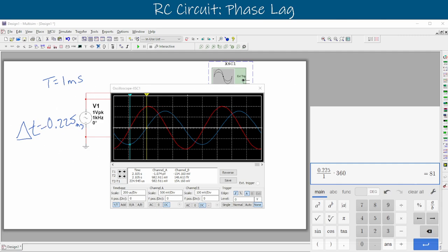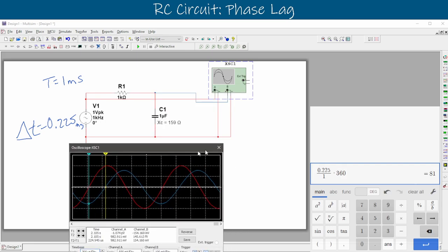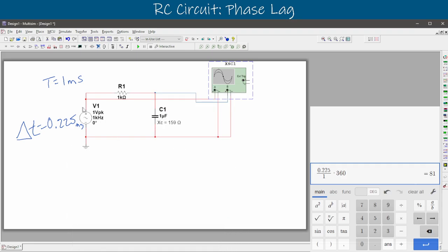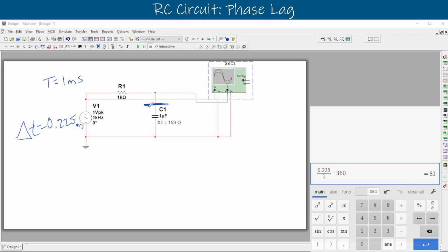So is this actually a high-pass filter, or a low-pass filter? Our signal is going to come up here through the resistor, and everything is going to be allowed through this resistor, but the capacitor is going to dump anything that is a high frequency across it to ground. And so we are going to lose all high frequencies to ground, right? Which means that the capacitor at the same time is going to stop any low frequencies from crossing it, and all low frequencies will be available across the resistor.